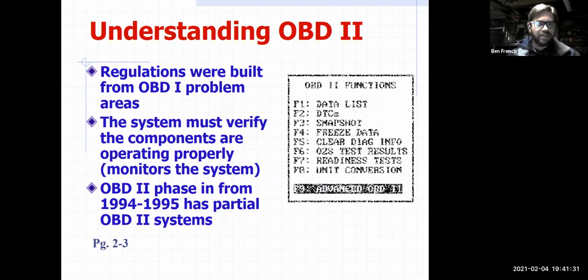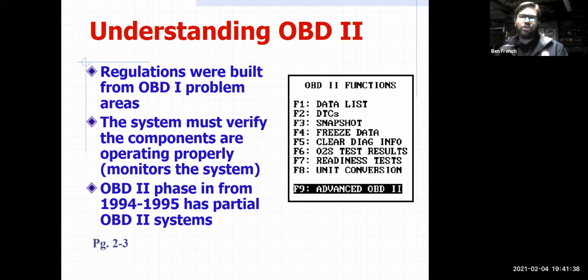So we set up criteria to do that. Earlier tonight, I was talking about, hey, I want you to leverage your OBD2 generic information. If you look at what's on the screen right now, this kind of old school scanner menu, this is like your OBD2 generic functions. You basically had 9 modes that the government mandated that the car manufacturers give you. And those 9 modes were what you see on the screen here.